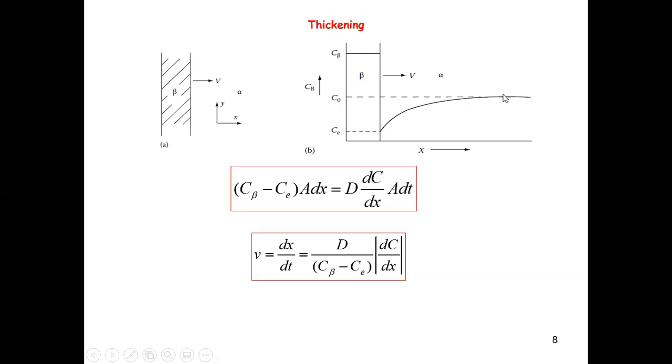the composition is increasing. So this derivative is going to be positive, but I'm here just to make sure that the velocity is positive, is propagating to the right. Okay, it is determined by a number of factors. The first one we see is always proportional to the composition gradient, right? The larger the gradient, the faster the transport, you're always going to get faster growth. And also it's linearly proportional to diffusivity, which is again a transport property. The faster the transport, the faster you can grow.